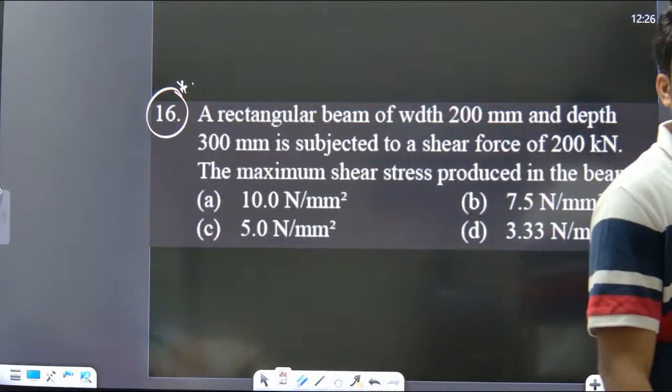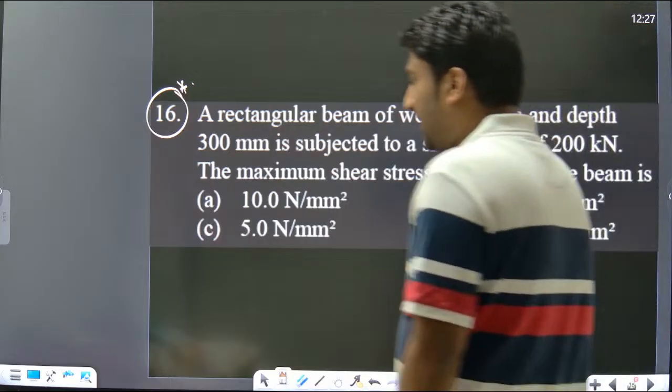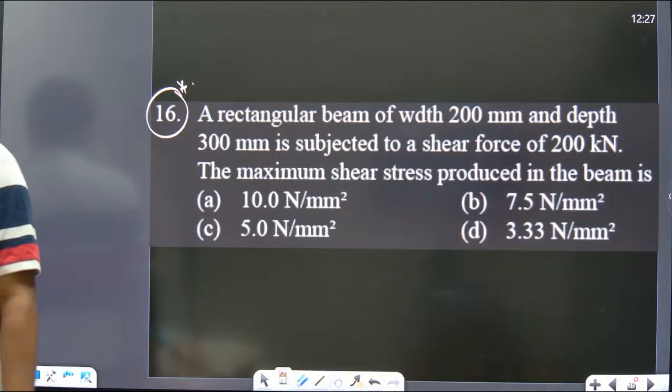Direct tension is 2 LD. Yes, very good, Vignesh. 2 LD or 30 mm. And what is the straight length of the lap? 15D or 200 mm. Straight length of the lap is 15D or 15 phi or 200 mm, whichever is more. Clear? So 3 values are there.